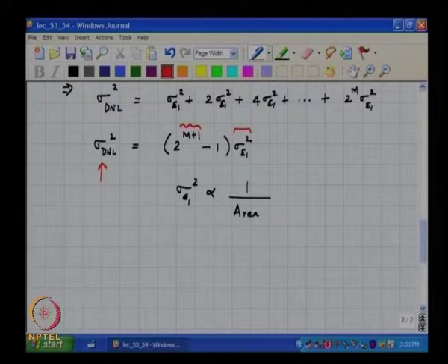And once we know what sigma E1 is, we can figure out how large we need to make the size of the unit conductance in this particular example in order to achieve that sigma E1. We still have not figured out though how one is going to choose m, which is how we segment the DAC. Does this make sense? All right.